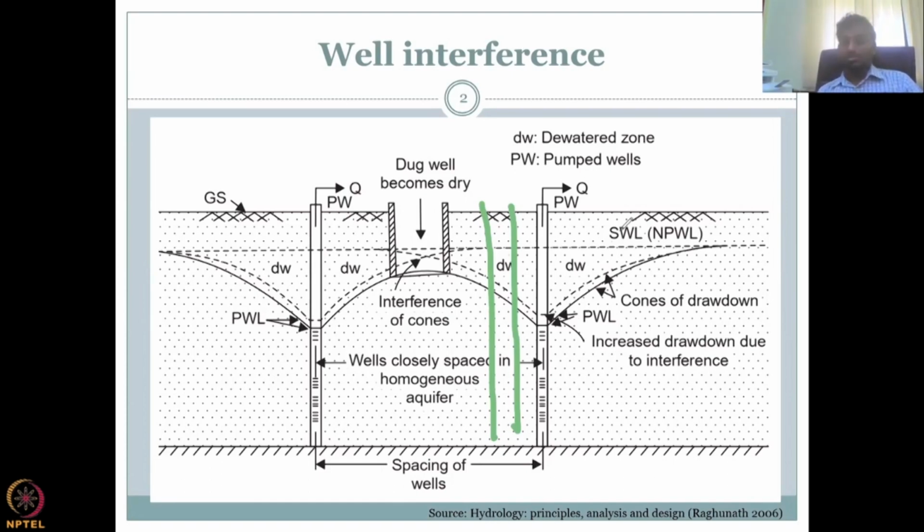So here the access to groundwater is cut, kind of like blocking a pipe supply through some blockage, or cutting the tube and saying no water for you. So that is what is happening. You lower it below the water table, and at one point the water does not enter the dug well and thereby doesn't recharge. So be careful when you do some field work.